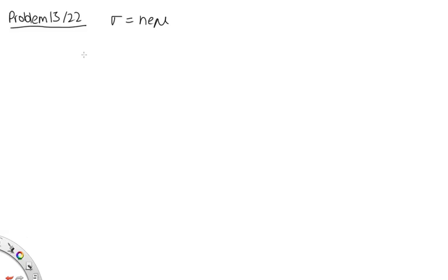Now, electrical conductivities just add together. So the total electrical conductivity is equal to the conductivity due to the electrons plus the conductivity due to the holes. For the electrons, we've got N electrons per cubic meter, e is the charge on the electron, and we've got mu_E here. And then for the holes, we've got a very similar expression. P is the number of holes per cubic meter, e is the magnitude of the charge on the hole, and mu_H is the hole mobility. So that is our expression for the electrical conductivity in this case.